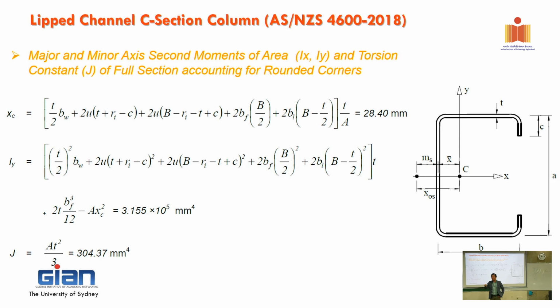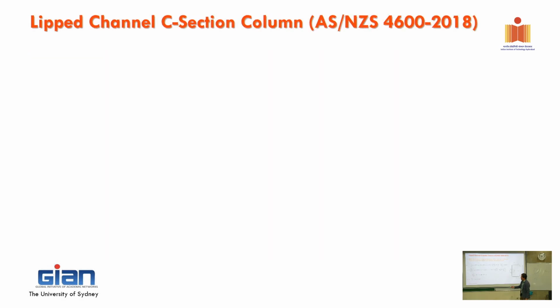What's that? Torsional. Yes, yes. So it's related to torsional rigidity, isn't it? So torsional. Right. So J here, and then related to J is IW. Right. So when we talk about bending, we talk about second moment of area, IX, IY, and then Z is torsion. And torsion, very important, and equivalent to that is IW, which is the warping constant. Okay? So we're going to have that later on.